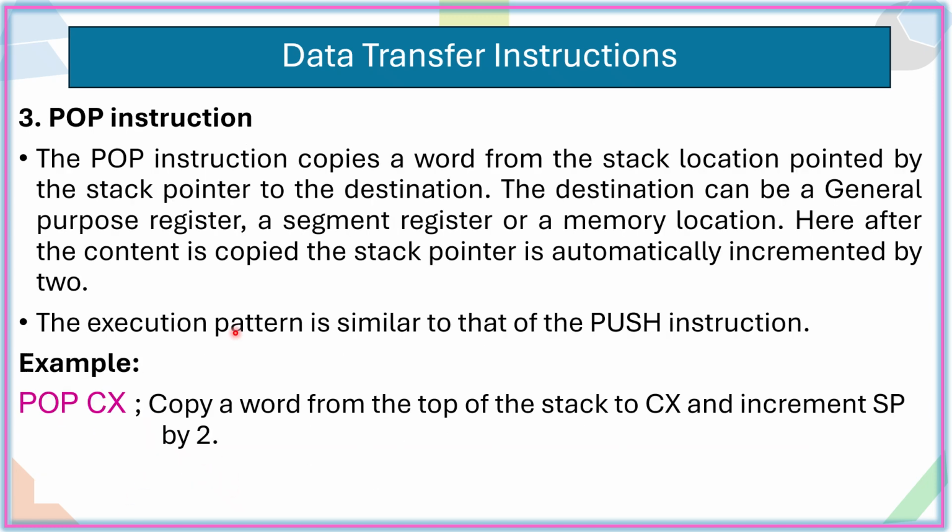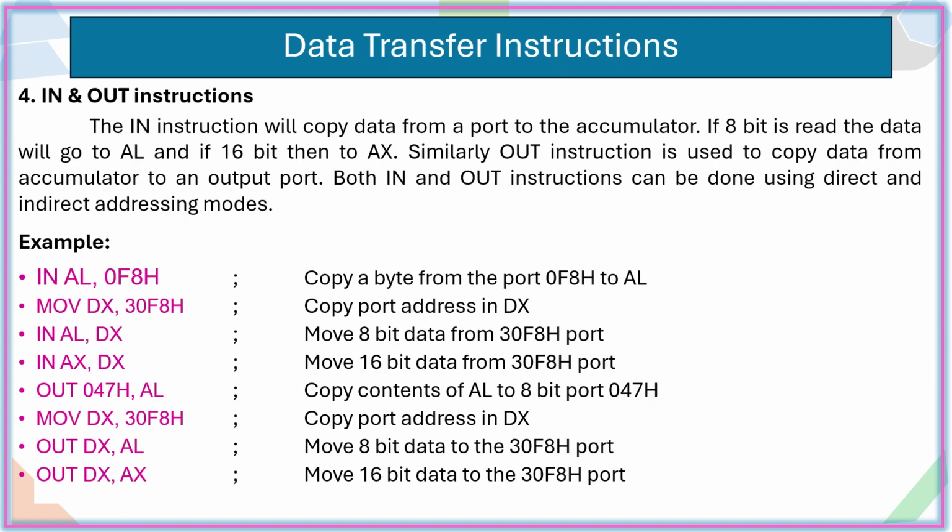Same as push, here it is going to pop, that is, it is going to take the content from the stack and move it to the destination register. So it copies a word from the stack, pointed to by the stack pointer, to the destination. The destination can be any register, like a segment register, memory location, or a general purpose register. The example for that is given here.